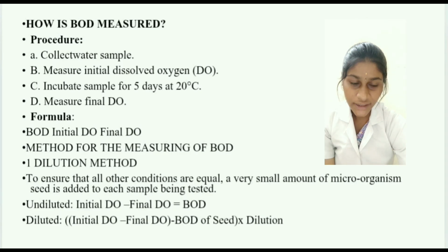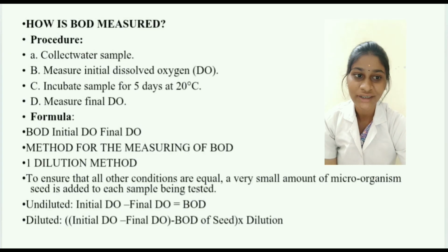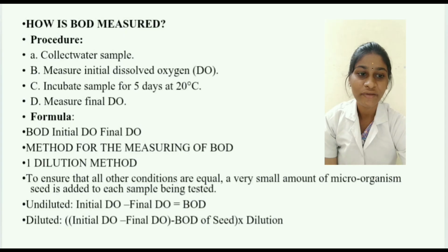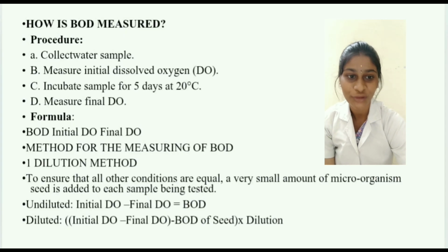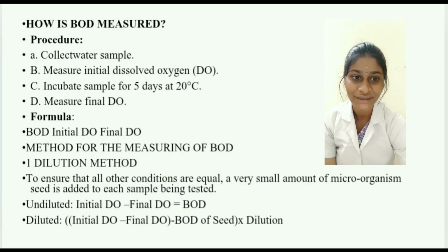COD test procedure. Preheat the COD reactor to 150 degrees Celsius. Add a known volume of the water sample, for example 2.5 ml, into a culture tube or COD vial. Add 1.5 ml of potassium dichromate, the formula is K2Cr2O7, as digestion solution, and 3.5 ml of sulfuric acid reagent to the tube. Cap the tube tightly and invert several times to mix. Avoid splashback of acid.